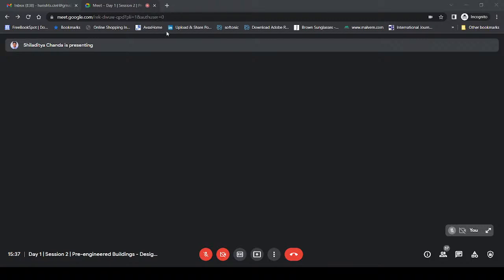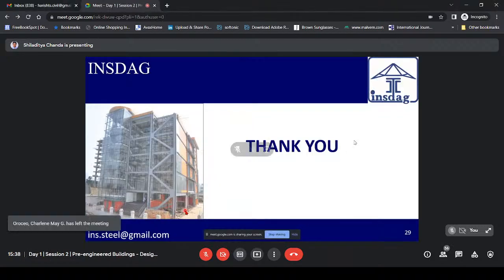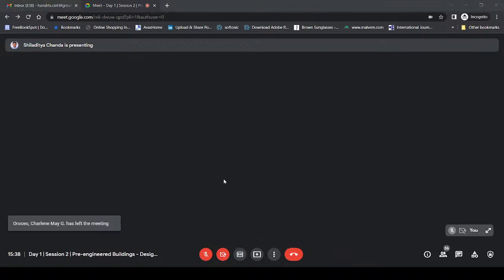Nowadays, in the Indian case, for rigid frames you need to consult IS 800, and IS 801 is still under revision. So these are the sort of inconveniences. People normally prefer MBMA, even the clients, because under one roof you get everything. On the contractor side, if they follow MBMA, they can achieve economies, and in the age of cutthroat business, it makes sense to go for MBMA.